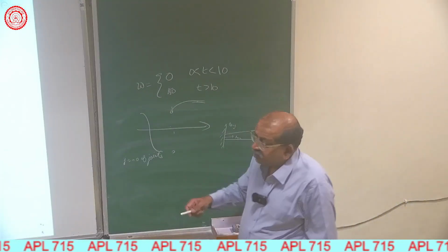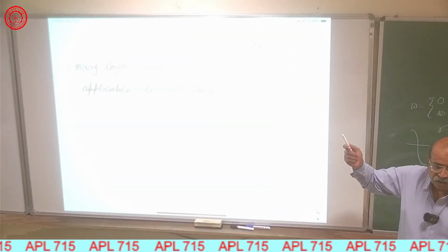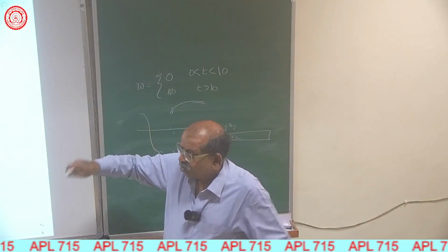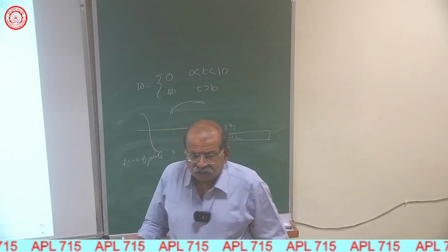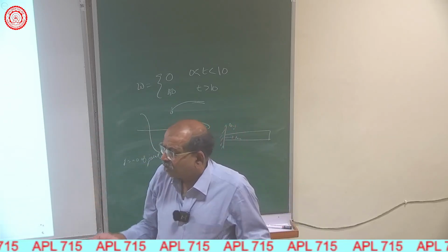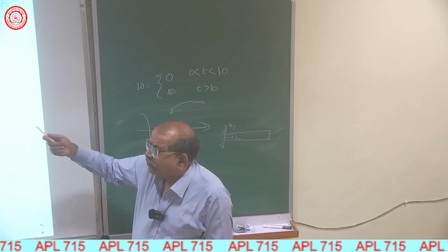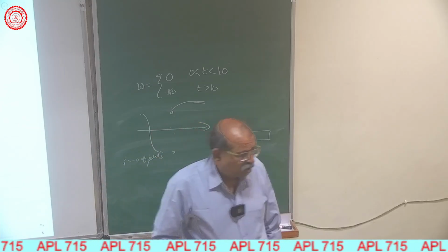Even if you do not know the mean flow, it has dUi by dxj. So you put it in and solve the mean flow equations. The dUi by dxj terms will go on with the other terms because ui has to be solved for. So it is applicable to all flows, even if there's a new type of flow. But the major drawback